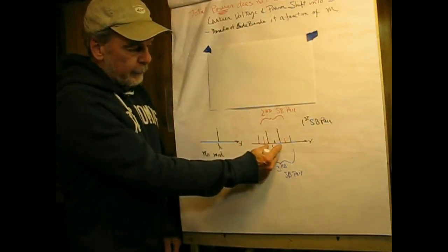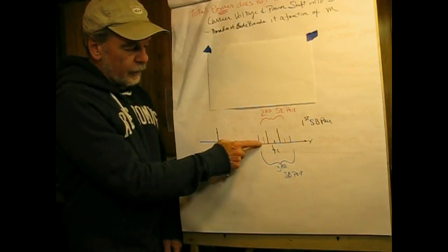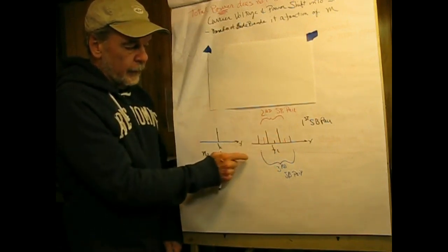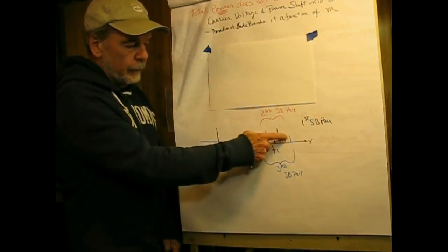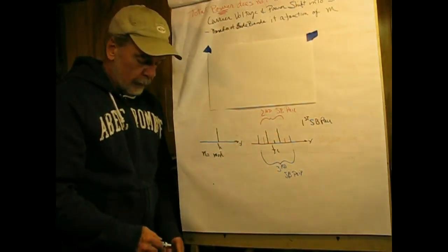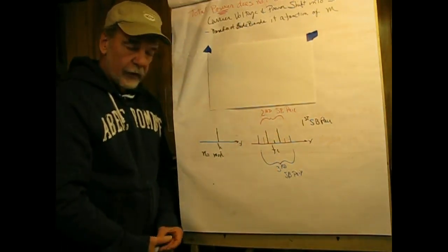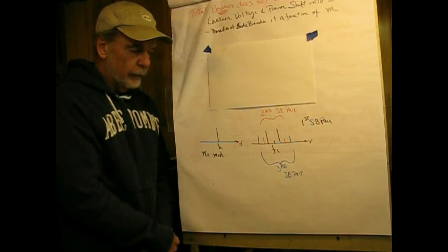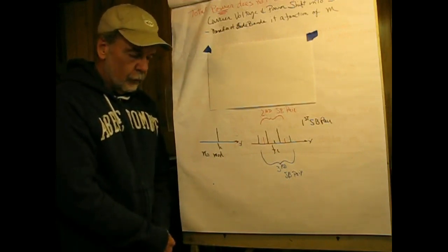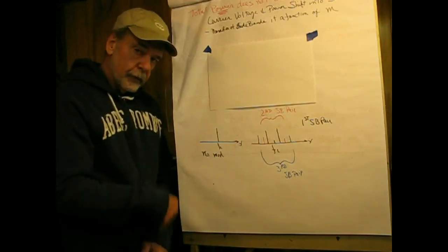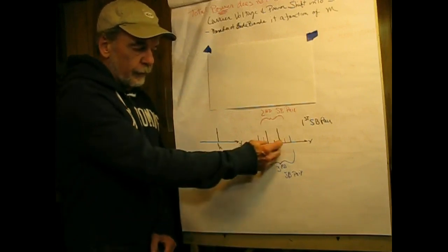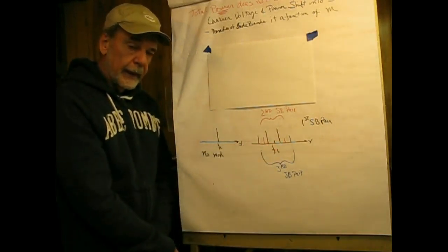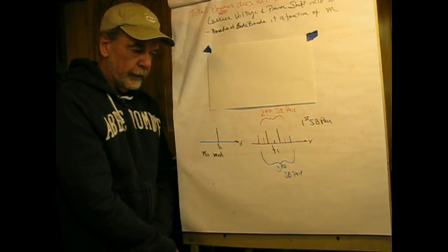The first sideband pair in black popped up, the second sideband pair in red appears, and the third sideband pair in blue also appears. So we can have many sideband pairs, or in narrowband FM, used in, say, taxicab communication, it's limited to the first sideband pair, and the bandwidth competes favorably with AM.